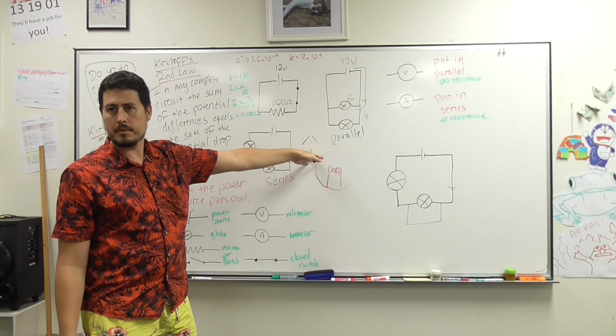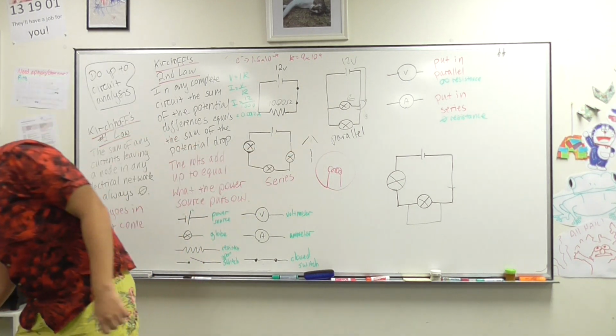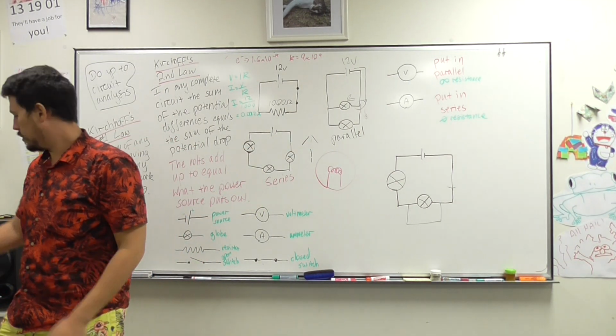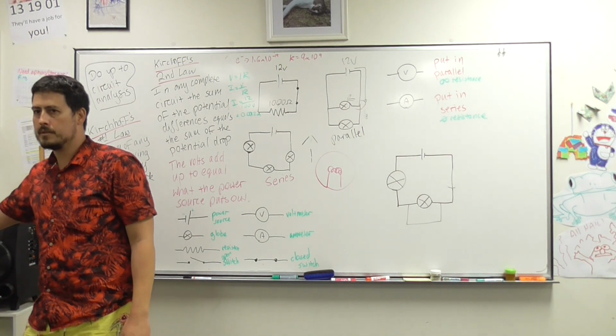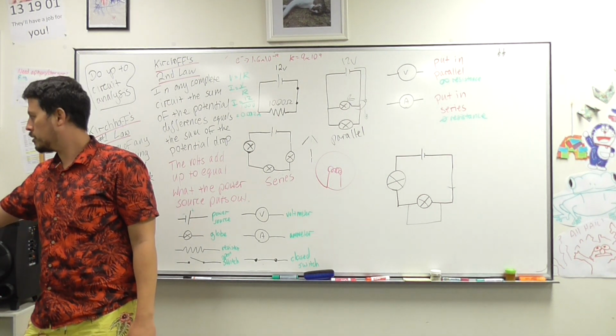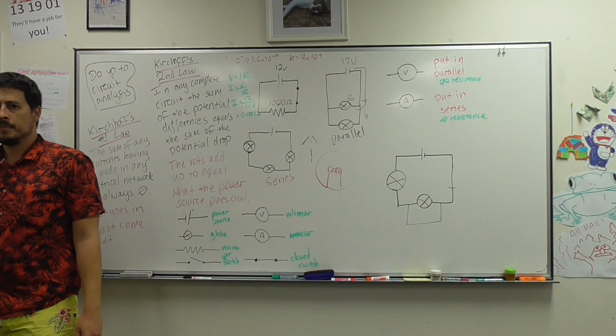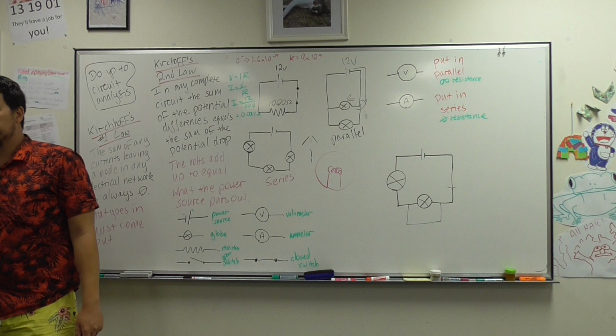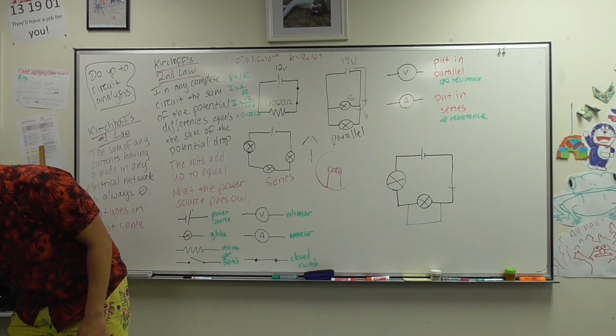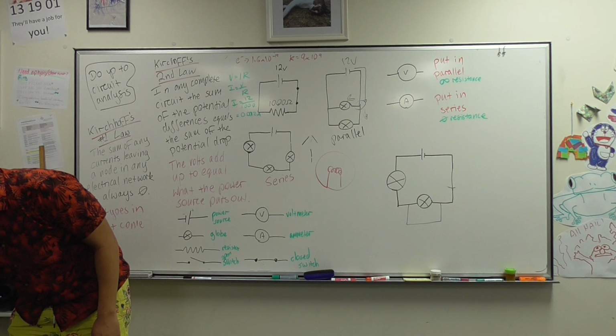The earth is important. Say, for example, this metal casing here, when I rewired the 1950s Van de Graaff generator, I've taken the earthing wire and I've actually screwed it into this metal casing. Now, if the 240 volts goes live on the metal casing and you touch it, and the only option for the current is to go through you, then it will.